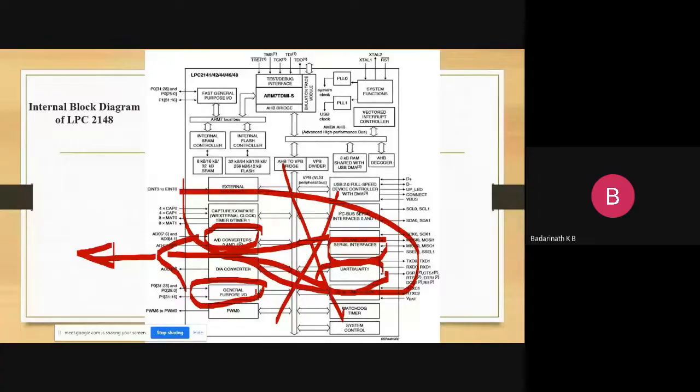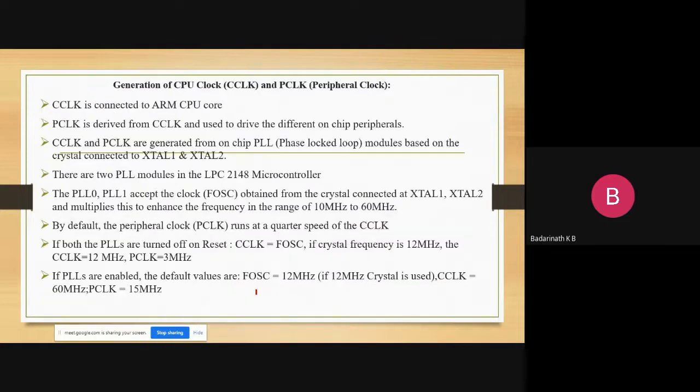So when you design a project, you should see how many GPIOs are required, how many ADCs are required. You should be able to negotiate what is required. You have to allot and then remove, allot and remove. You have to do some experimentation on what is required for you. Then you will be able to come down to a final solution: these are the pins I can use for this logic and everything. So this requires some experimentation whenever you design a project.